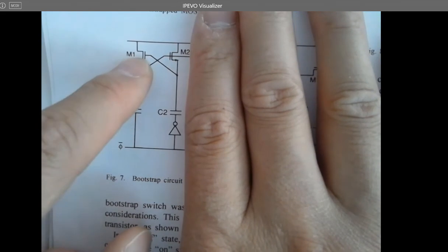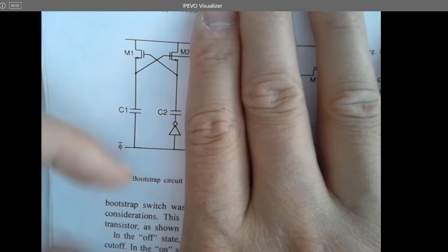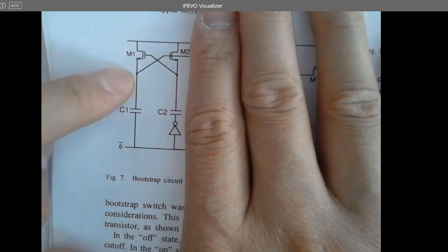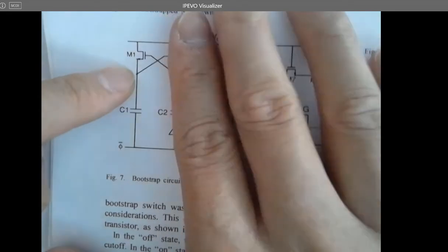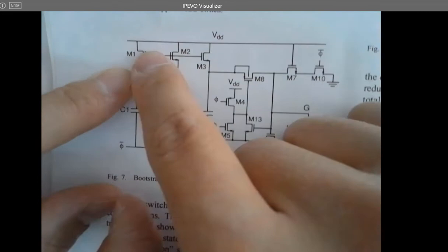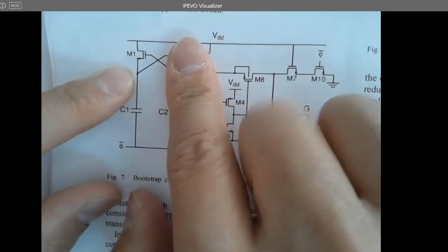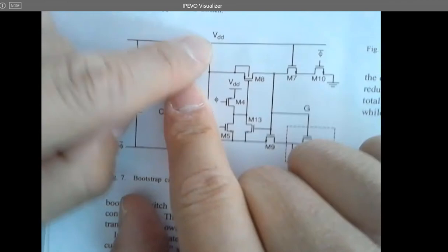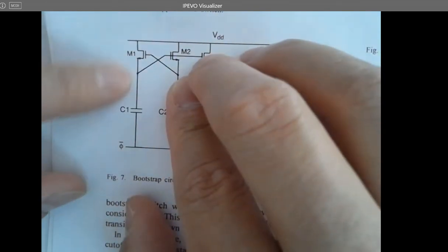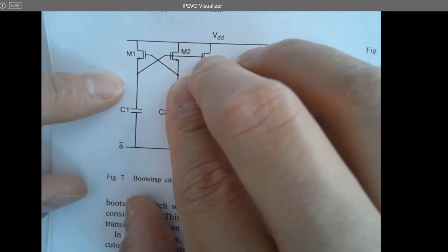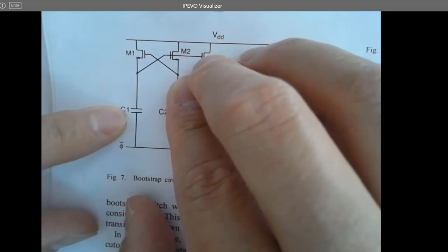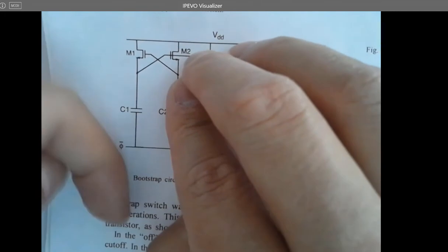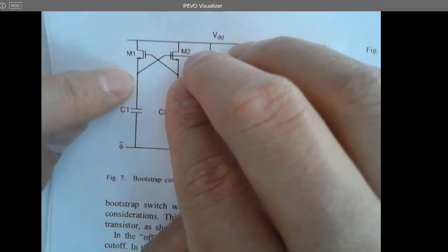which means this is a higher voltage being applied to the gate of this transistor. So whenever this is pulling charges down, what's the maximum voltage that can be pulled to this node by this transistor? Assuming that we have a larger VG here for this transistor. So whenever this is pulling, what's the maximum voltage that can be reached at this point? Just directly VDD, because you only have VDD on the top rail. Whenever it's pulling, the highest voltage, or whenever this is going low, the voltage being transferred from here to here will be VDD.